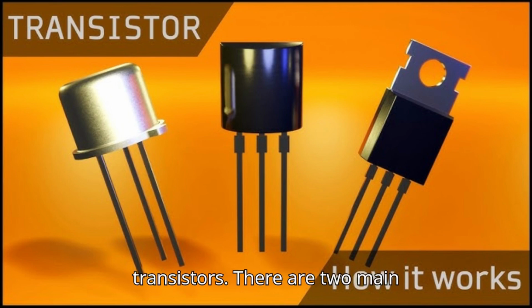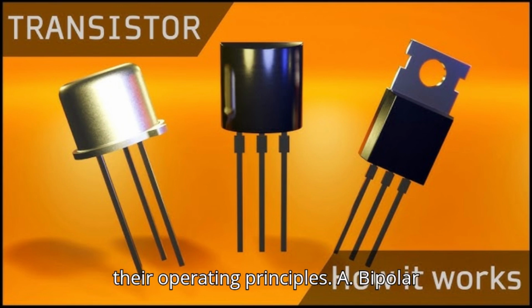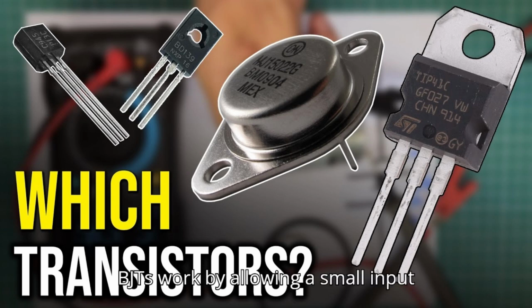2. Types of transistors. There are two main classifications of transistors based on their operating principles. A. Bipolar junction transistors, BJT. BJTs work by allowing a small input current to control a larger output current. They are bipolar because both electrons and holes participate in conduction.